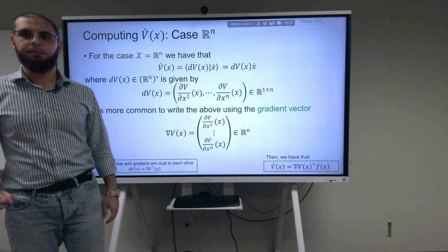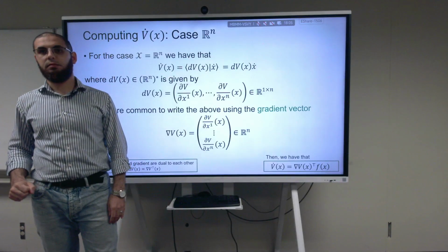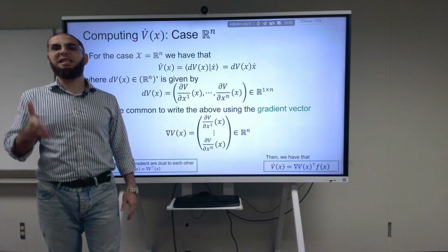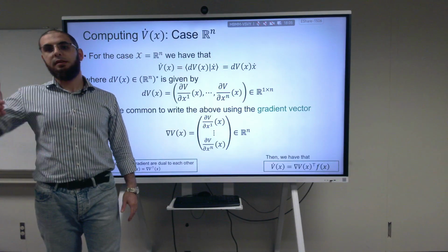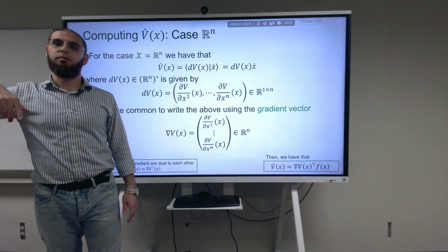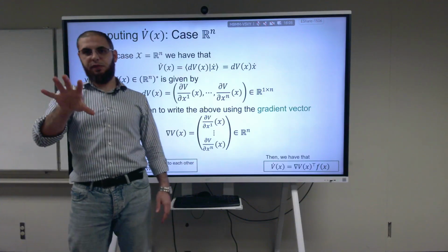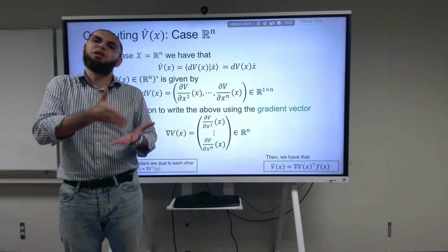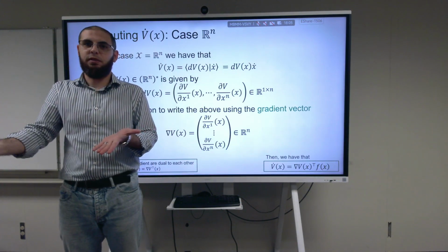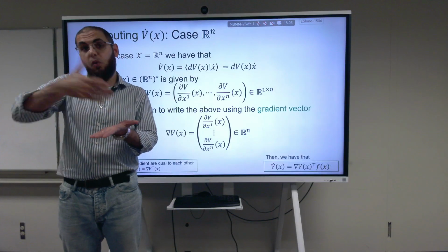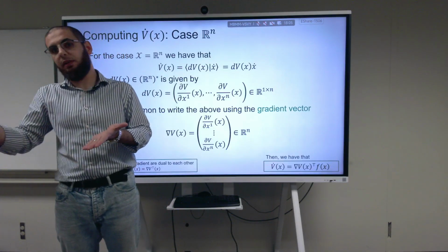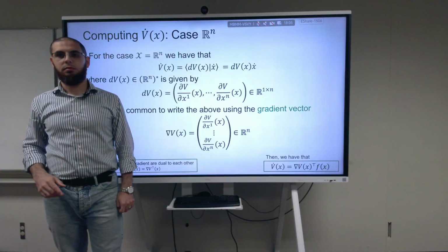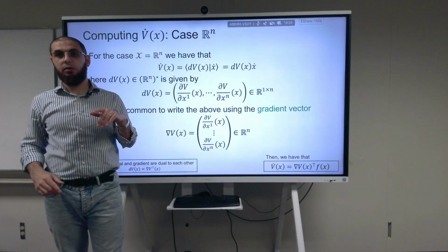If, let's say, one phase works, can we go for the same function for stage 2, or would we have to choose another function? For example, if you cannot show stability, the other criteria were stronger. If I choose a function and I cannot even show it's positive semi-definite, can I show it's positive definite? It's actually a requirement: for a function to be positive definite, it has to be positive semi-definite first. So this way we cannot go, and this way, yes, you can go.